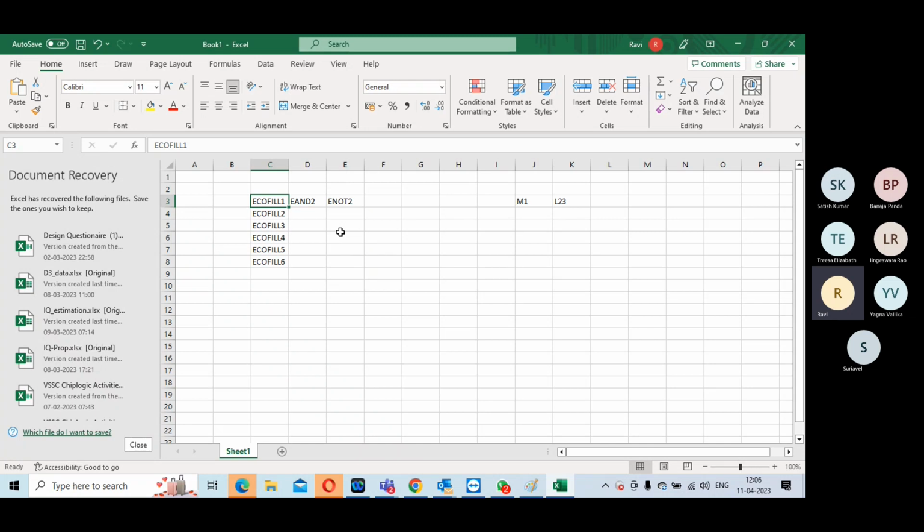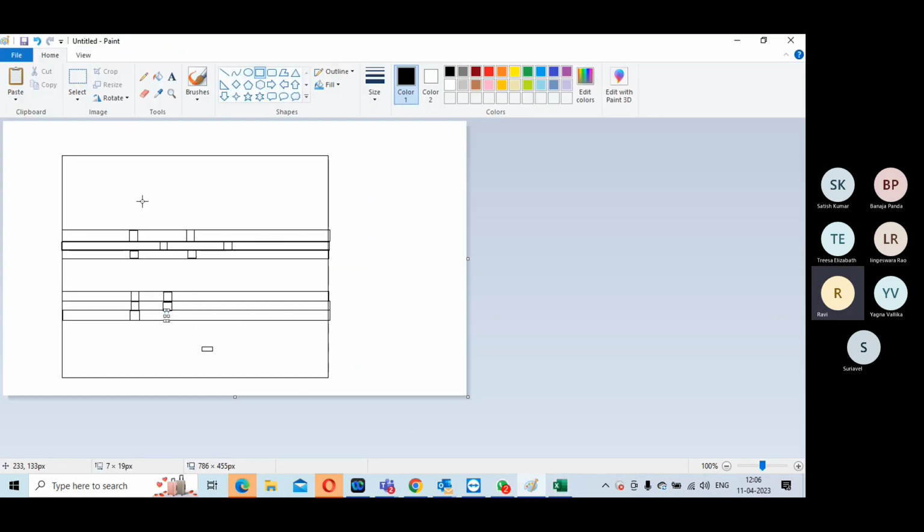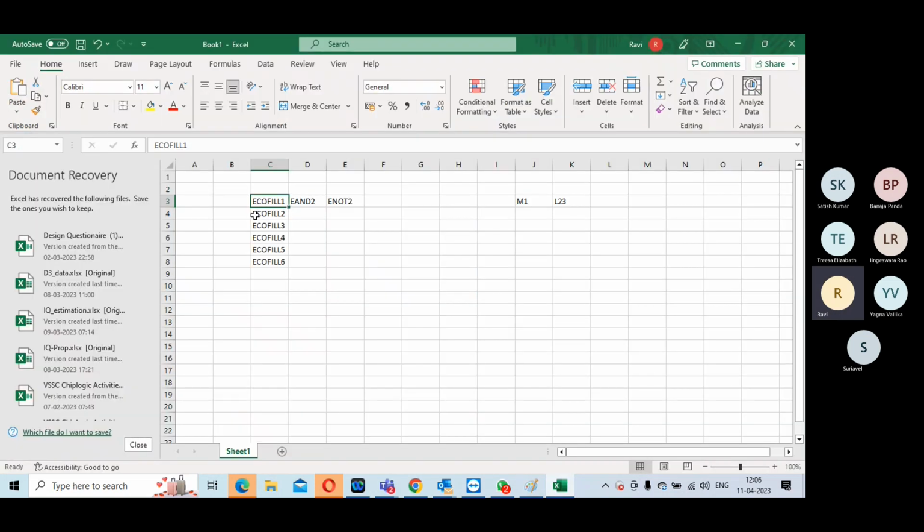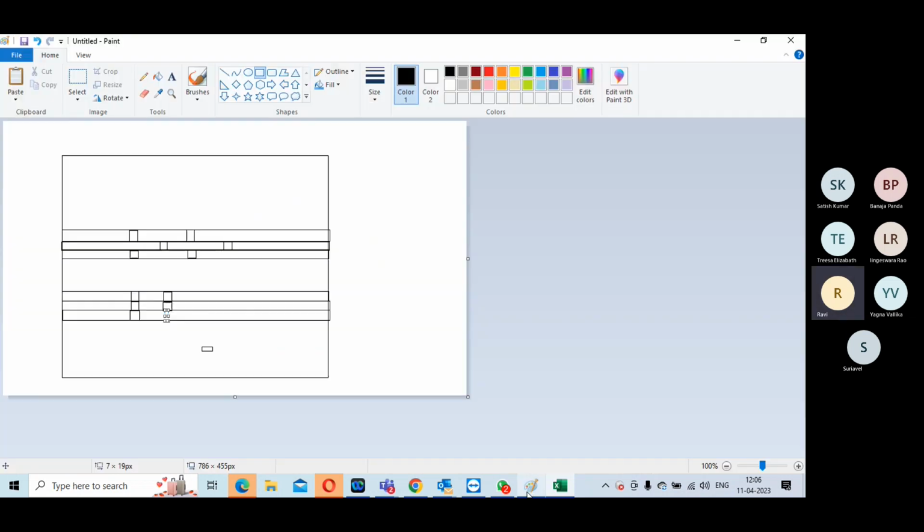Or the other idea is, as I was saying, this one is all part of force fill, right? You have no control where it is going to get placed. This tool will place automatically wherever it finds space, because it is a dense region. But when I know by design that I have some very critical paths which are not tested or done properly, there could be timing challenges.